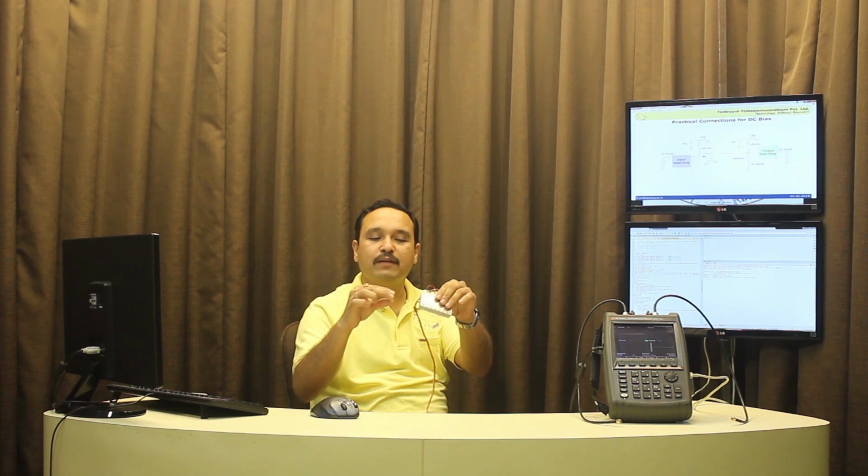And finally, you have to build a PCB and enclose it in a nice fully enclosed metallic chassis, because you don't want any external interference entering your amplifier. Everything which comes from your coaxial cable should get amplified at the output and no interference should come in. And while applying DC, of course, using a DC feedthrough is definitely recommended. So with that, you would complete your low noise amplifier design.